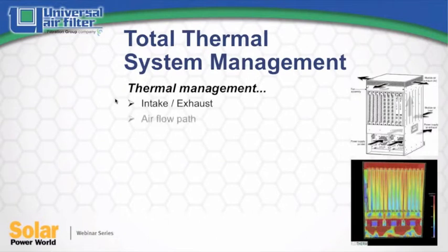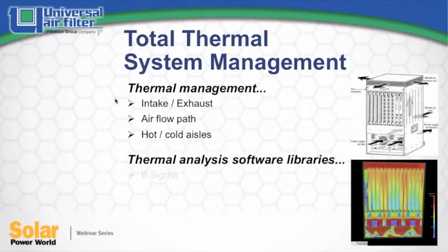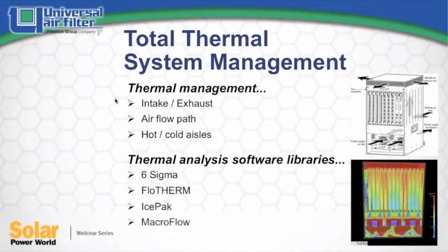Moving from physical enclosure designs, there's also thermal management design considerations used to dissipate harmful heat buildup in densely populated chassis. Thermal analysis software packages are used to simulate equipment thermal characteristics and calculate the effects of less restrictive and more restrictive air filter media on overall system pressure drop.